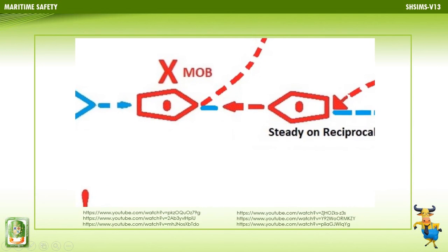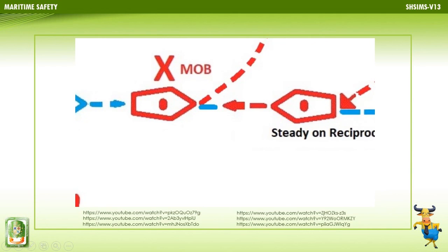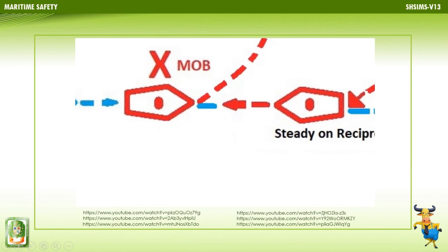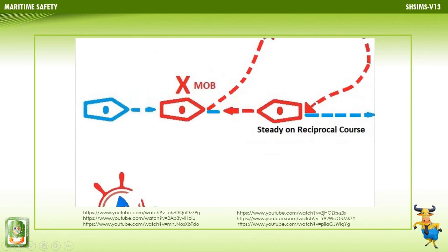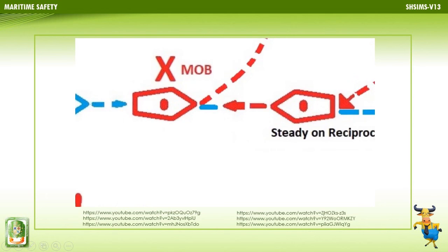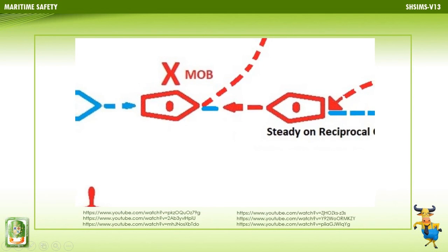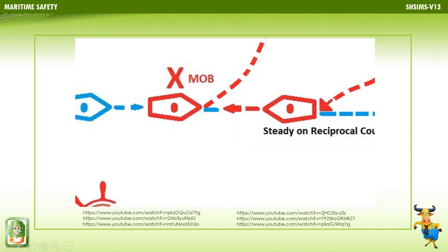The size of the turning circle also meant that merely turning 180 might put the vessel on a reciprocal course, but it would be nowhere near its reciprocal water track. To execute a Williamson turn, the same speed is maintained throughout the maneuver until the vessel is on its reciprocal course. The vessel is first turned until the heading is approximately 60 degrees to 70 degrees from the original course.